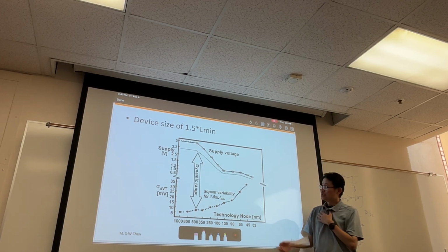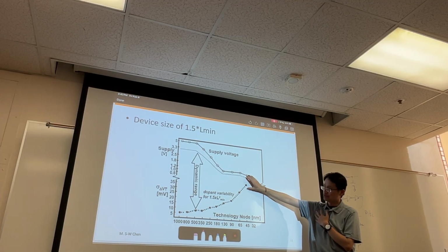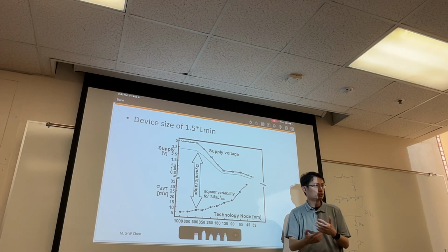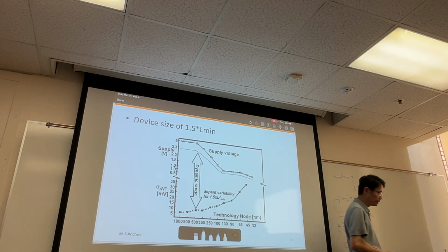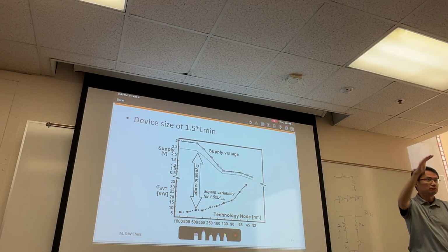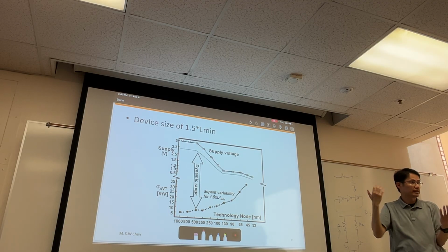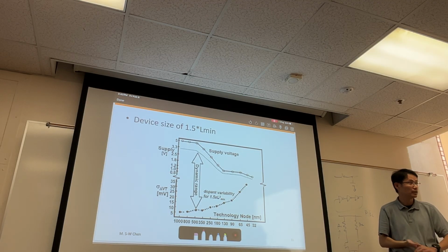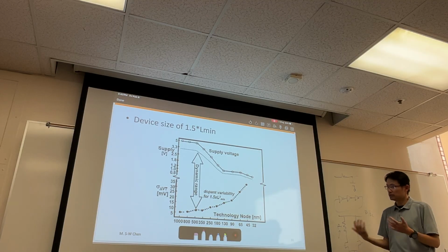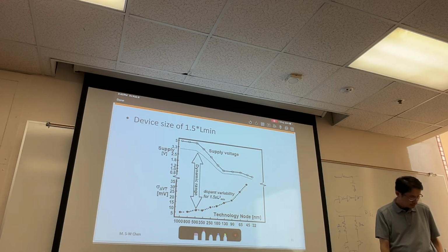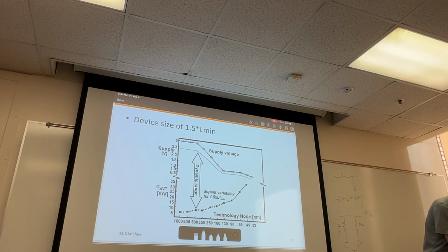Okay, so this is really the challenge for circuit designers, especially analog circuit designers, right? So as your matching becomes worse, you're going to have more variation. But my maximum is my VDD. VDD is capping the maximum that I can go, right? So if you're off too much, there's really not much that we can do, right? So that's really the kind of reality that we are facing.